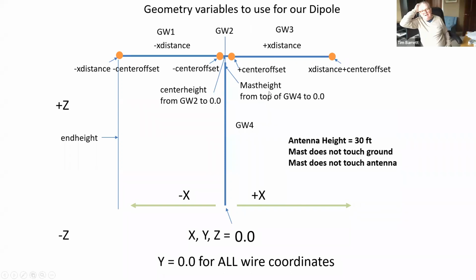All right. Okay. So your question is another great question, because the very first time I ever built a vertical, I was unaware that NEC 2 doesn't support antenna components at or below ground. So I put a bunch of radials in slightly below ground, and I sent out my results.